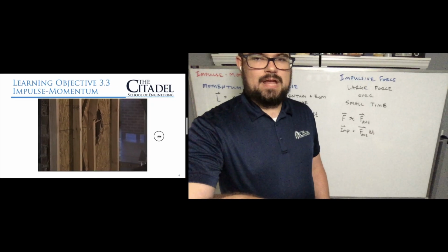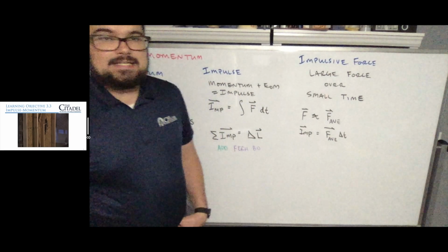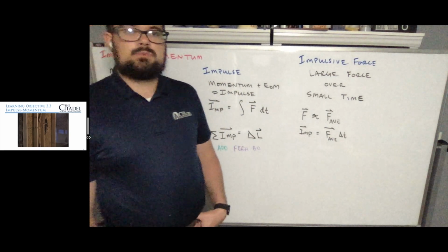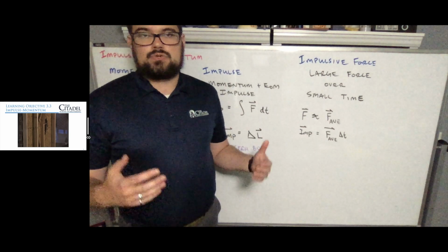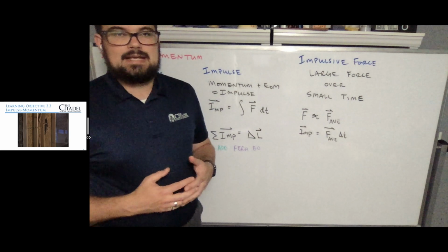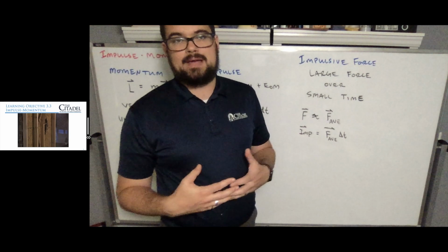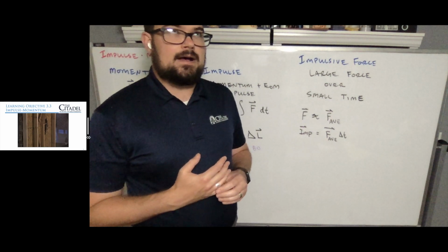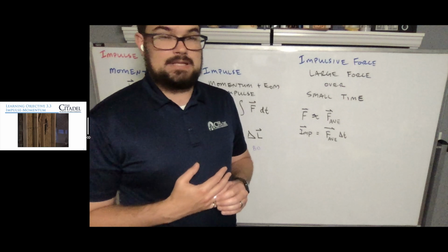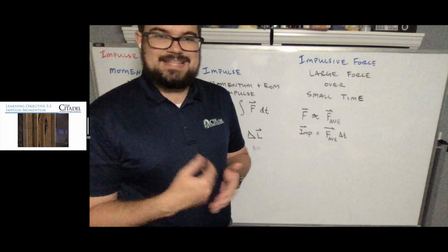So that video came from Texas Tech University. Texas Tech University is known for its debris impact testing because that's the way we classify tornadoes. So we design tornado shelters for debris impacts. Typically those 2x4s were all flying at about, I think it's 125 miles per hour, when they hit the walls, and we look at ways that we can resist that motion.